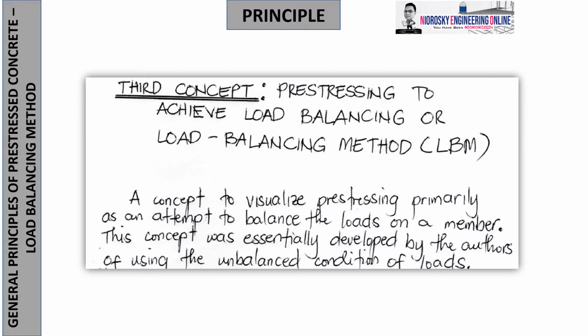Actually kasi when we have a beam, let's say, let us remove first yung tinatawag nating tendon. So therefore, the beam itself has self-weight and or some additional load. So therefore, it will be the immediate load to be carried by the beam, and most likely it will be the source of deflection, or most probably the stresses to be identified within the beam. Now, as we install the tendon, most likely it will produce some counter stress that may influence the upward direction of the deflection, resulting in a probable unbalanced condition.